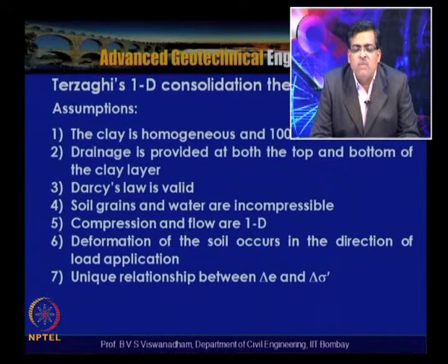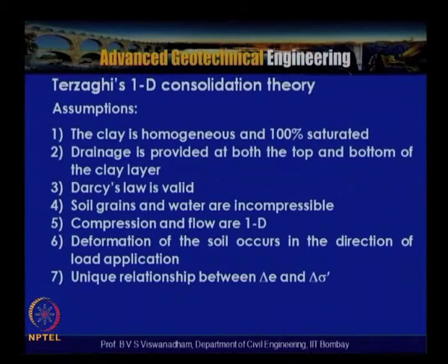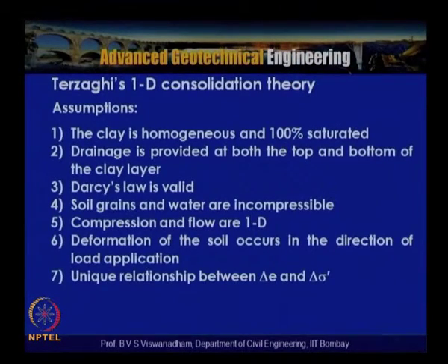So here the deformation of the soil occurs in the direction of load application, and there is a unique relationship between delta e and delta sigma during the process of consolidation. So the deformation of the soil occurs in the direction of the load application, compression and flow are one dimensional in nature, the soil grains and water are incompressible, and Darcy's law is valid. So here the relationship between delta e and delta sigma is given.